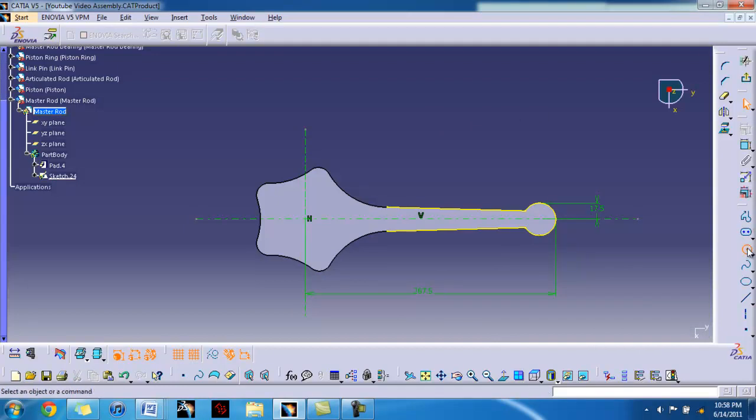And from there you're going to draw a circle right on the center of those. Make sure both axes are highlighted orange. And your radius is going to be 63 divided by 2. Alright, next is to complete the sketch. So from the end point of both lines, create a horizontal line to the circle, just making sure the line's blue. There's the top one.